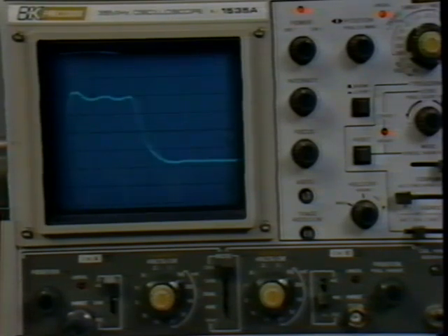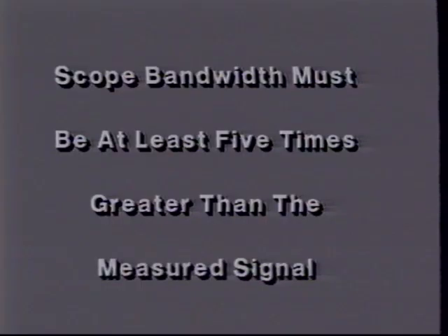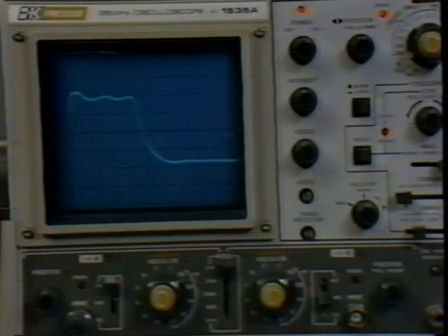The reason for this is that square waves are composed of a large number of faster sine waves. As an example, a 35 MHz square wave has significant components of up to 175 MHz. Practically, this means that to display a square wave properly, the scope must have a bandwidth at least 5 times greater than the square wave's frequency. If you measure a signal outside the scope's bandwidth, the oscilloscope will still display it. However, do not attempt to align any signal that is outside of your scope's bandwidth. The error in the display will not permit enough accuracy to make any measurement correctly.